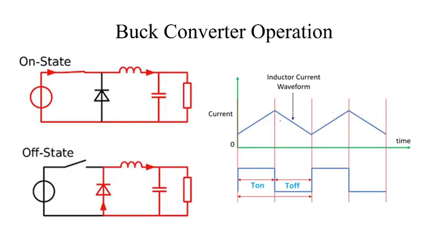About the operation of this buck converter, when the switch is on, in the first figure you can see here, this is our first diagram. You can see here during the on state, when the switch is behaving like a closed switch, input DC power is supplied to the load through this filter. This is our filter circuit, LC as a filter circuit, and the power which is supplied from the input is going to the output.